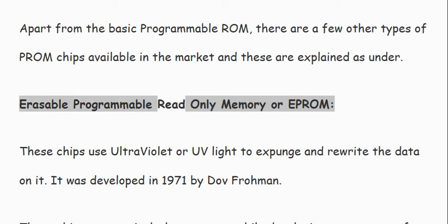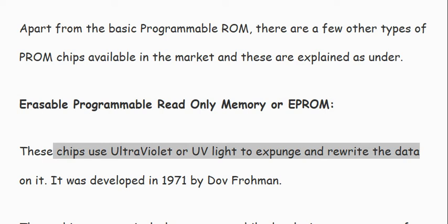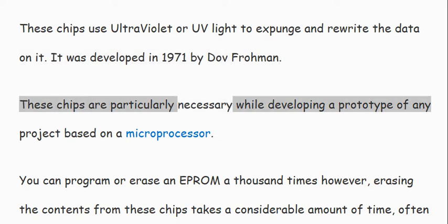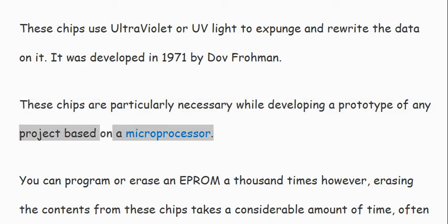Erasable programmable read-only memory or EPROM. These chips use ultraviolet or UV light to expunge and rewrite the data on it. It was developed in 1971 by Dov Frohman. These chips are particularly necessary while developing a prototype of any project based on a microprocessor.